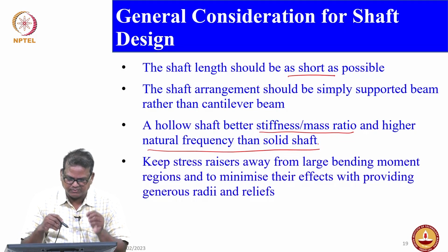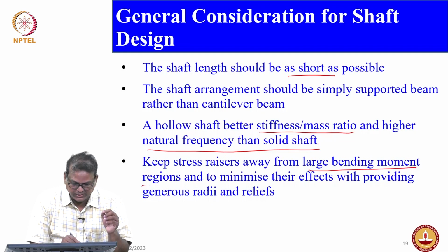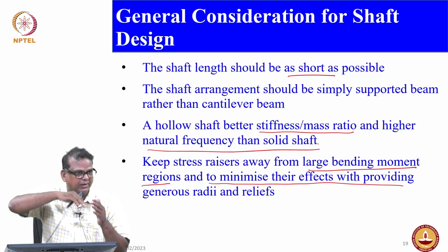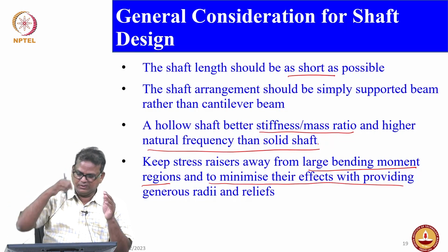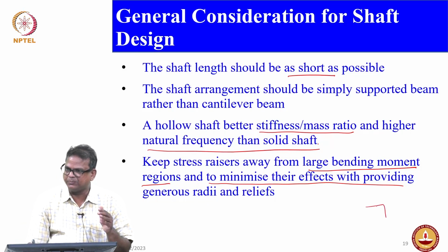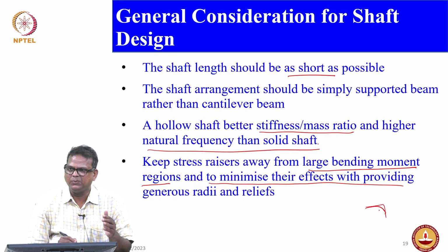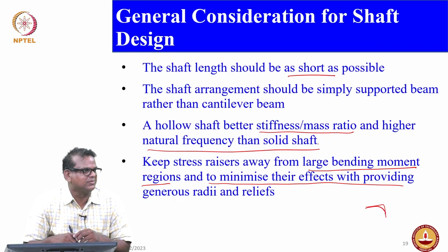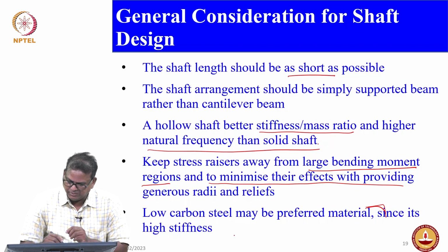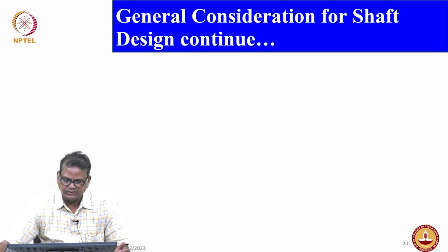Keep stress risers, I am talking about stress concentration, away from regions of larger bending moment to minimize their effect, by providing generous radii and reliefs. Generous radii mean that instead of having a step like this with a sharp corner, it is better to blend it gradually like this. By doing that, you avoid stress concentration.